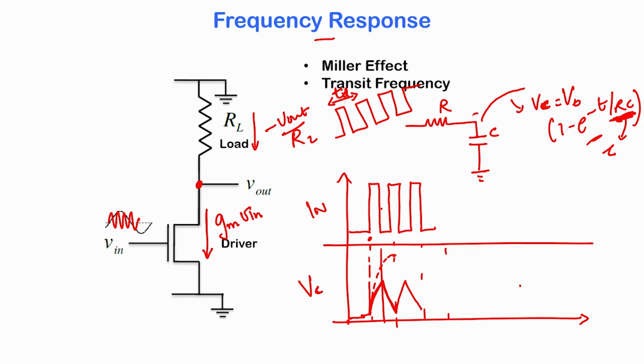And therefore if you look at the magnitude of the voltage here, and if you take the gain of the circuit, say the Vc by Vn, you will find that the gain has gone down, because Vc is not climbing up to what it was climbing up to, because the frequency has increased. And therefore if R or C increase, then the time constant increases and the circuit cannot respond to your high frequency input pulse. So in other words the gain of the circuit will start going down. Okay, so that is enough introduction.